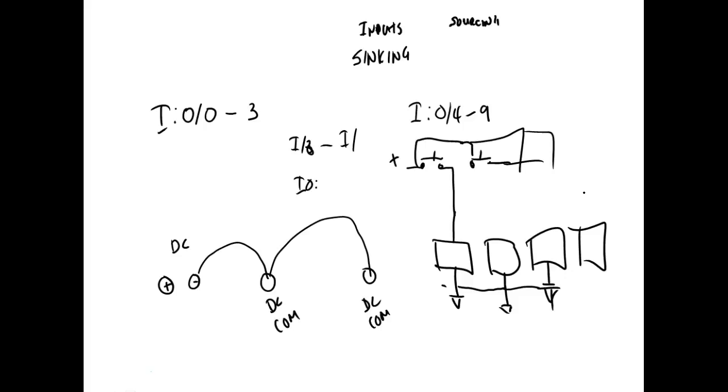Of course, once you establish a neutral, you stick with that. This guy here, we have to establish one of the AC lines. Of course, normally, this guy here has relay outputs. What's nice about relay output? It doesn't matter if you use AC or DC. You look at the contact rating. Most of them will run up to like 440 volts if you use AC. And then another thing you need to look at on your outputs is the current rating on that pump, right?